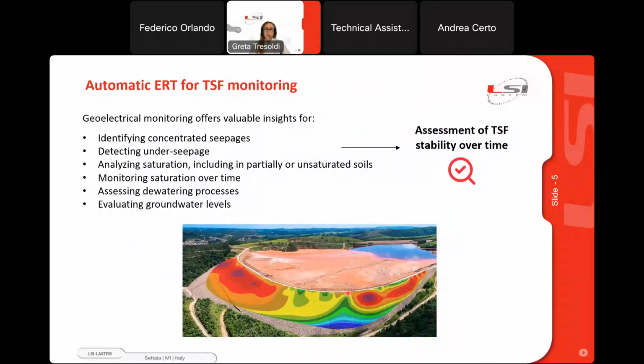A step forward, so how can we use ERT for TSF monitoring? Geoelectrical monitoring offers valuable insights for different water-related processes. So identifying concentrated seepages, detecting underseepage, analyzing the saturation over time, and not only in the saturated zone, but also in partially saturated and unsaturated soil, because the electrical current can travel also in the unsaturated soil, so it can provide information on the percentage water content in the unsaturated soil.